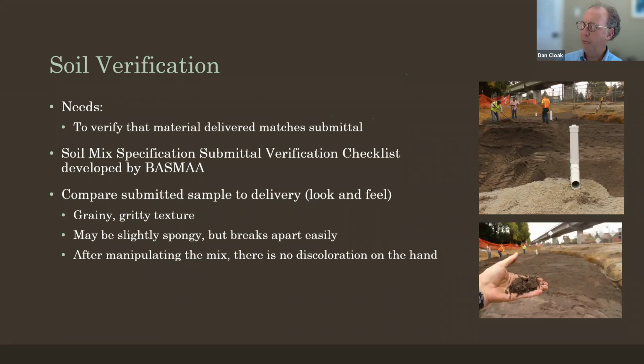The problem with that is that even a very small percentage of clay, certainly anything above 5%, but I think even less can be a problem, is that there is an interaction of the clay particles with the sand particles. Anyone who is a gardener and has made the mistake of trying to mix sand into a clay soil in order to loosen it up knows it doesn't work. What happens is you get kind of an effect of turning it into concrete.